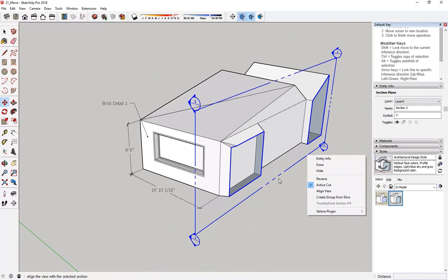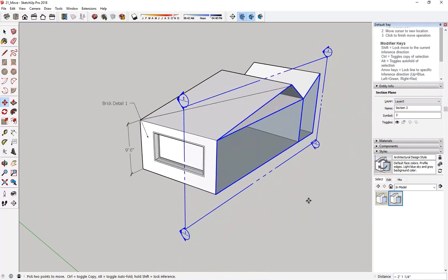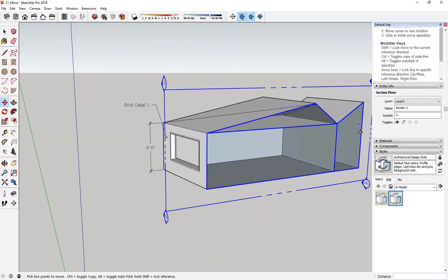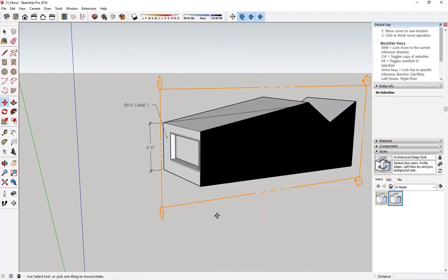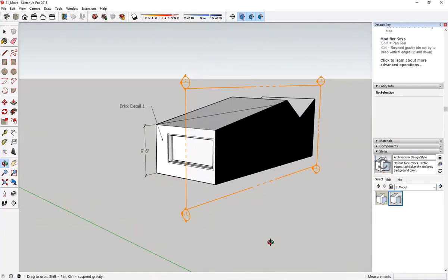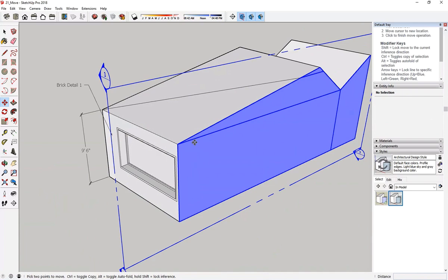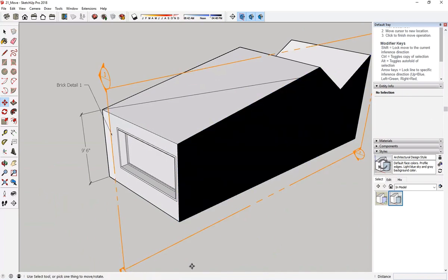The other thing that you want to pay attention to is that there are multiple ways of dealing with this section. One is that you can just leave it as it is when you're working with it, or sometimes you want to have a solid fill, so you use something like this. So let me just leave that as it is, and that's basically creating a solid section. And right now it doesn't make sense, but if I start creating the wall system within, then when it shows the wall system, instead of showing it as a hollow section, it creates a solid wall system, and it shows the rest of this as a drawing.